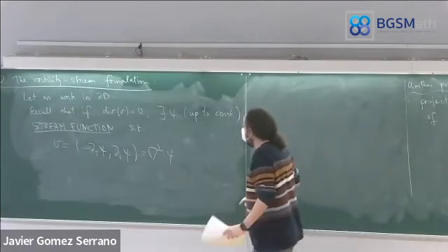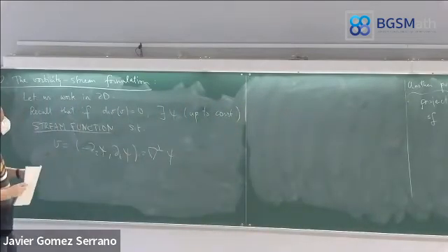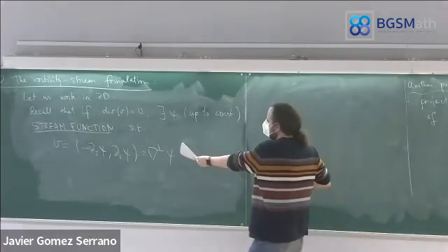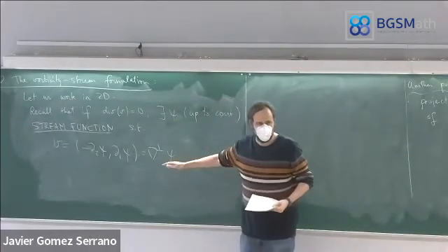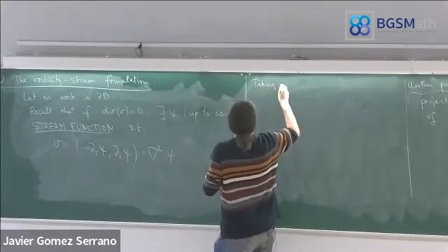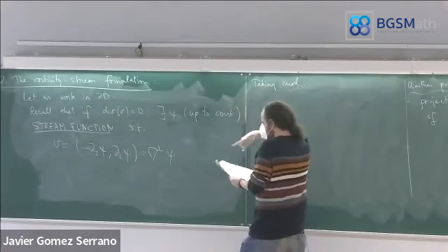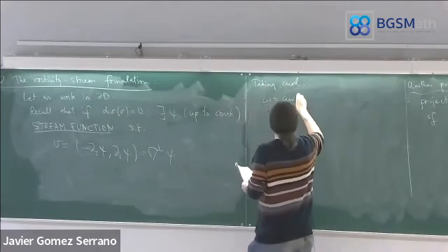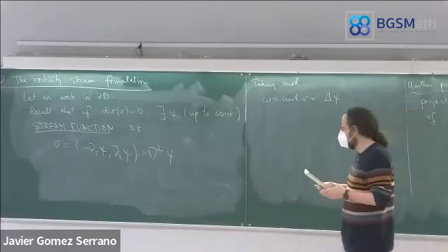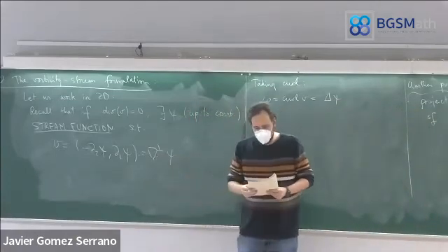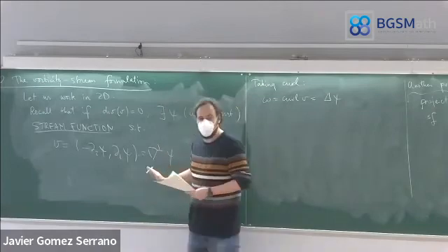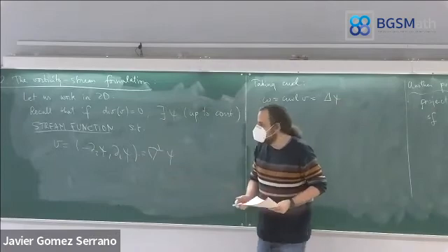Okay, so far it doesn't look as if this is too helpful. Let's see what is the equation that ψ satisfies. Let's take the curl of this equation. I want to relate the stream function with the vorticity. If I take the curl, then on the left, I get omega, and on the right, I get the Laplacian of ψ. So now I have a nice formula for ψ in terms of omega, and this in turn is going to give me a nice formula for V in terms of omega whenever I hit it with a perpendicular gradient.